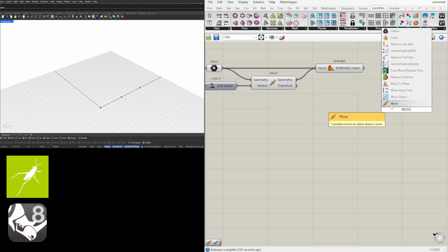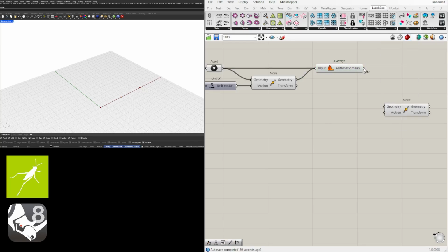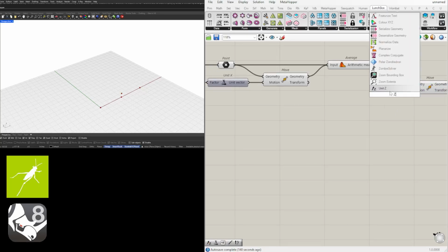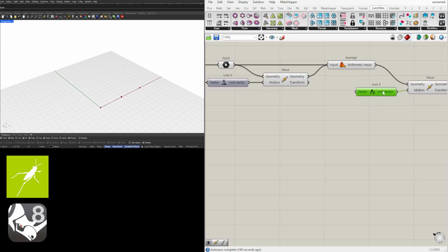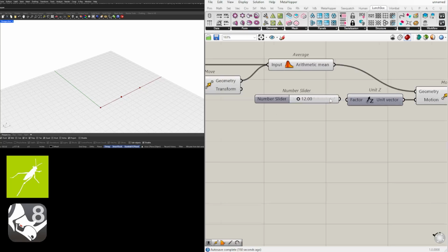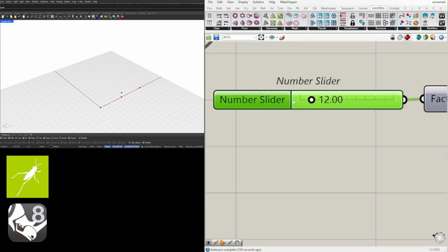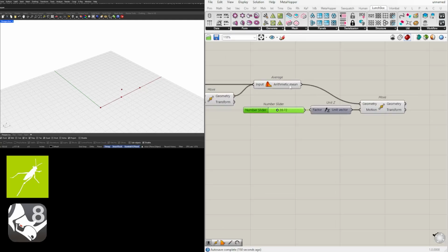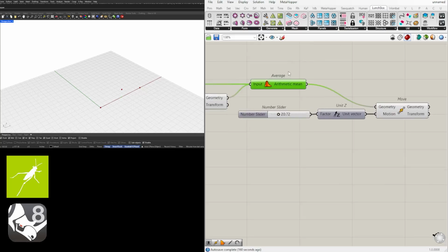So we're basically creating an arch and it's going to be defined with 3 points. So we'll move this geometry up in the Z direction. And we'll create another slider here to move it up by whatever number you want to pick. So now here we have this point that moves up. So we can technically hide this average point because that's kind of old.